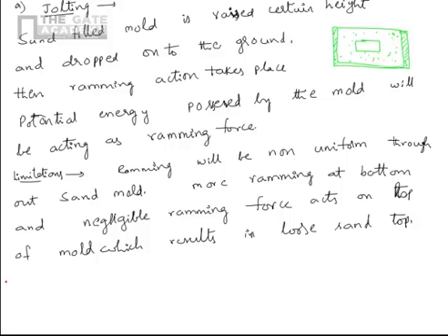To avoid this, there is another technique called squeezing. In squeezing, by using a plate whose dimensions are equal to the mold dimensions, we put this plate on the molding sand and apply a large amount of force by using a hydraulic press.